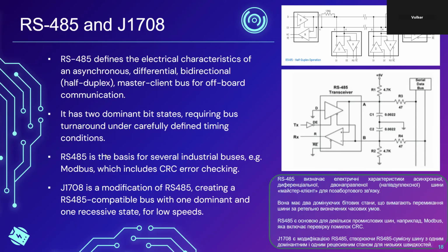So that was a problem with those microcontrollers. 8051s were part of it. Modern microcontrollers, the STM32 series, have features, including automated features, that will turn off the transceiver right after the last stop bit has been clocked out. So in modern microcontrollers, these issues that I'm mentioning are not really a problem anymore.